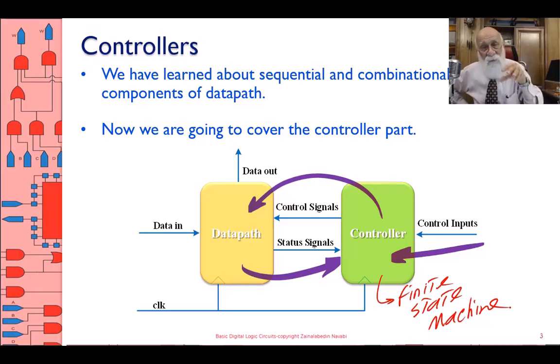So we take a simple finite state machine, not with too many inputs, not with too many outputs, with one input, with one output, and we exercise that. We show you the Verilog description of it. We show you the hardware implementation of it. Because if I have 4 or 5 states, one input, one output, I can easily turn that finite state machine into what we already know, which is flip-flops, Karnaugh maps, Boolean expressions, and show you the actual hardware right in front of you.